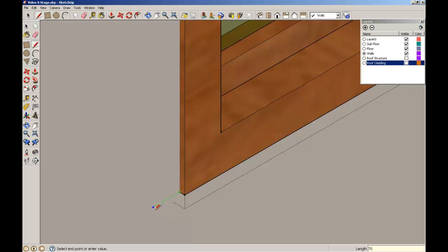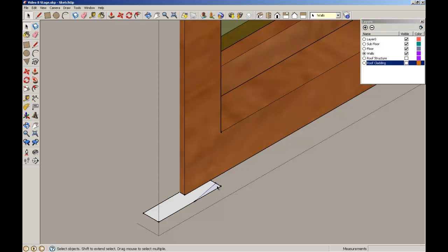I'm just going to do a very simple profile, across 70, 30, another 50 across here, bring it back to that edge, bring it back to that corner, and then close it off. Going to make a fillet through there, so then I can just delete that corner. So that's going to be the element that I'm going to extrude around the window.